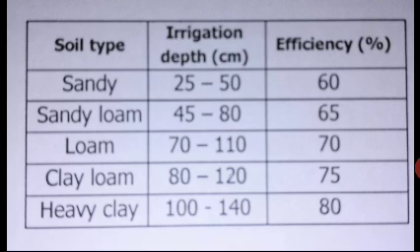The various factors considered in fixing the intensity of irrigation are climate, soil, topography, cropping pattern, drainage, groundwater condition, amount and nature of available water, socio-economic needs of the area, water application method, rain and its distribution, etc.